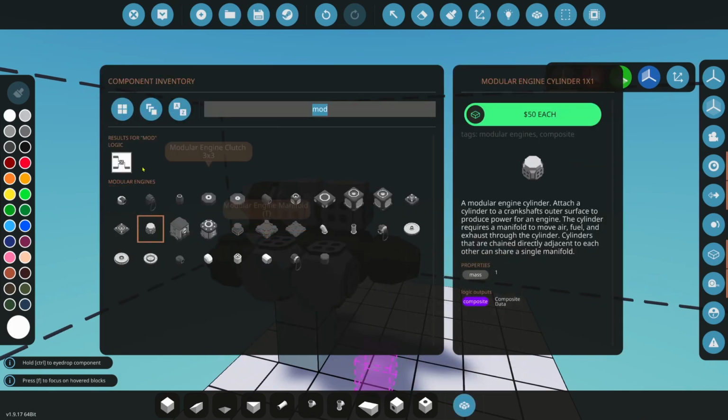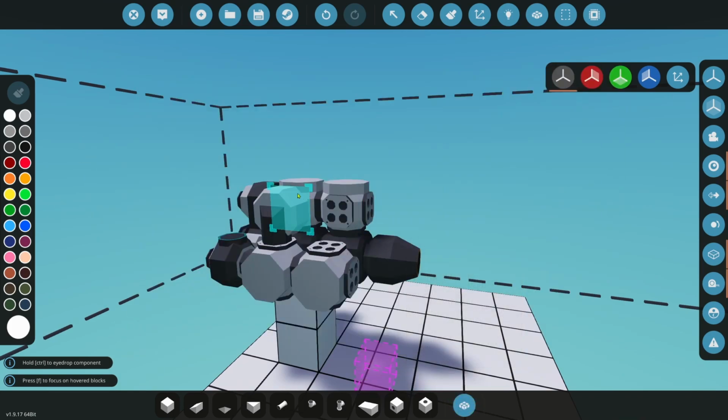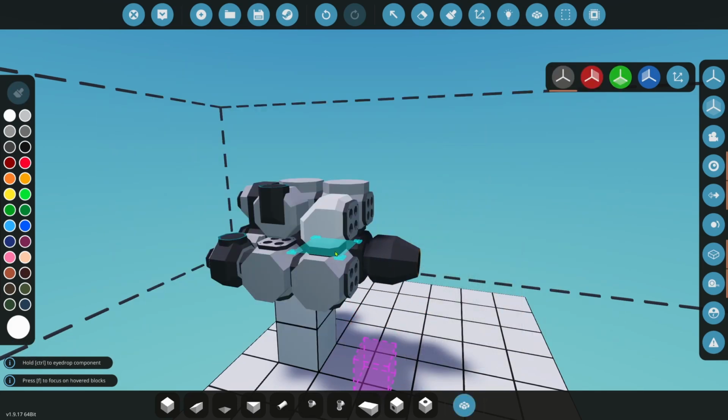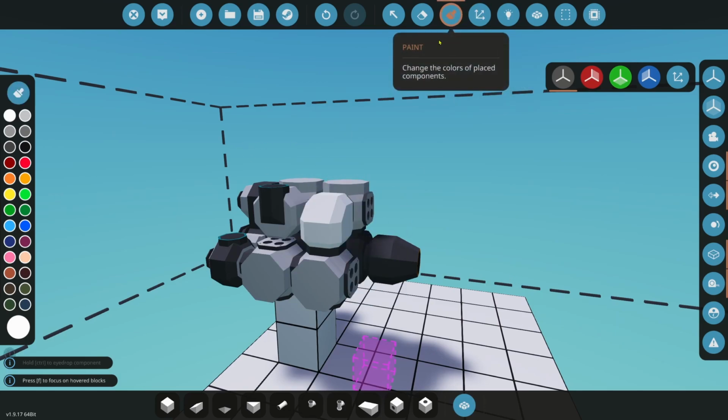If you put your air manifold on like this, the air is going to pass through here, it's going to go into this cylinder, and it will go into this cylinder, but it has no way to get to these cylinders. So these will get air, but this will not. So that's where these manifold pieces come in. If you wanted to make it a 4, you'd have to do something like this so that there's a path for this to travel. So it travels through the air manifold, through this cylinder, through this cylinder, through this manifold piece, and then attach. So you have to attach all those.